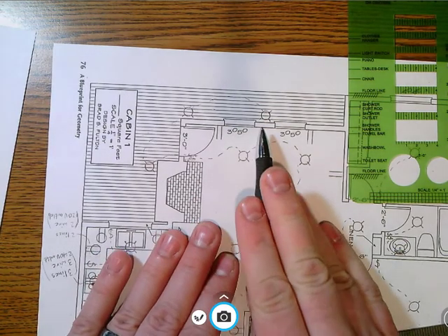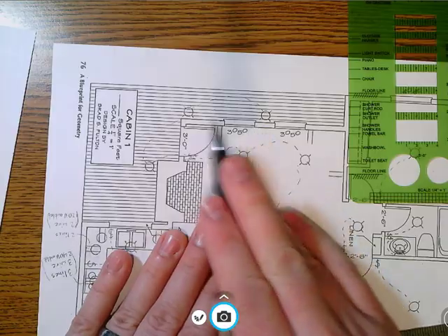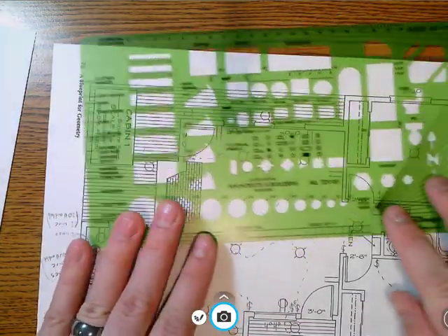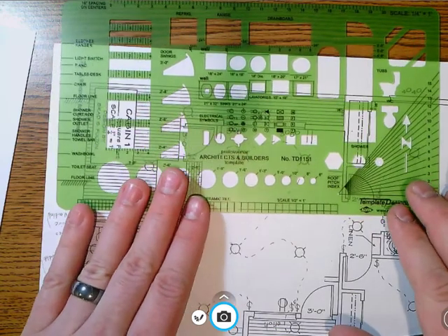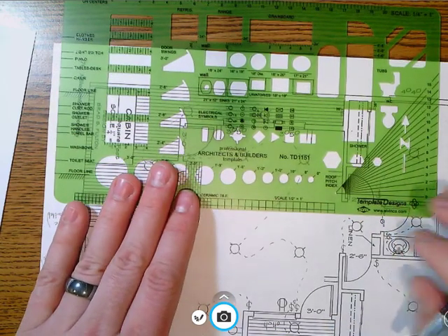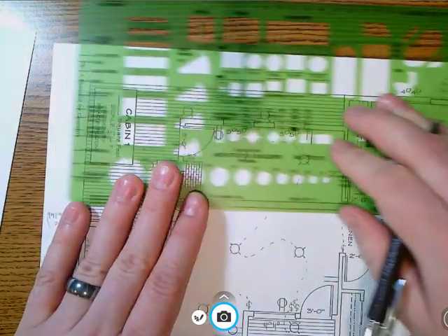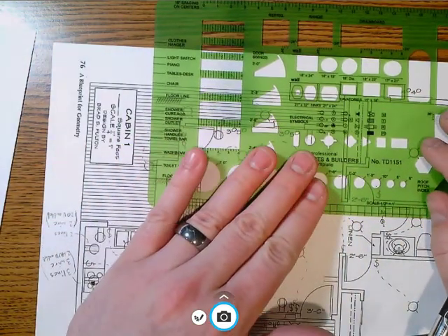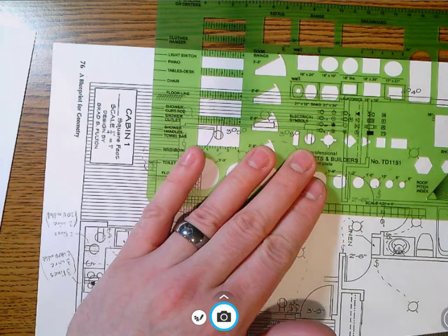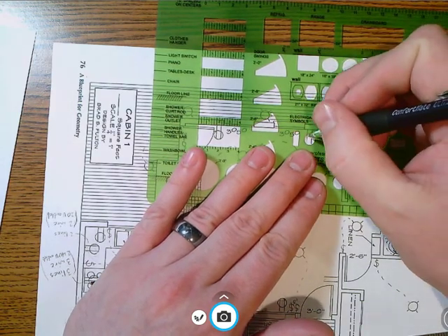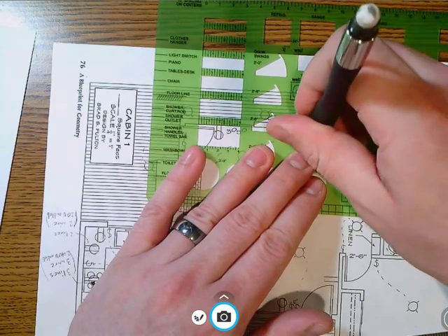The idea is, if you're here, are you at least 6 feet either way from an outlet? What I've seen students do in the past is they literally put an outlet every single 3 feet apart from each other, and that's a lot of outlets. If you're even thinking about the material aspect of it, you're talking an extra $10 for each outlet that you're trying to put in.